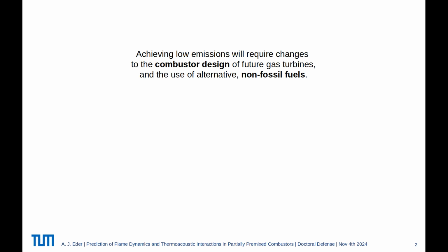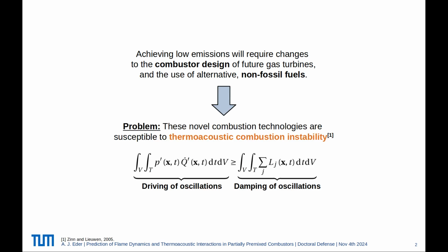Achieving low emissions will require changes to the combustor design of future gas turbines and the use of alternative non-fossil fuels. This is something we all know and what will happen. However, there's a problem. These novel combustion technologies are susceptible to thermoacoustic combustion instability, which can reduce operational flexibility and performance and in extreme cases lead to the destruction of individual components or the entire system.